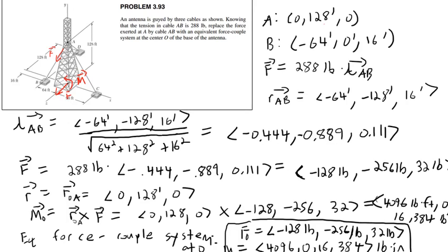Yes. So you're never going to try to change the force. You're finding the moment to balance that out. The question is, we'll never try to change the force, right? Yes, if we're just asking for an equivalent force couple system, no, we'll never end up changing the force. All that we do is add a couple to compensate for moving the force to a different location. Other questions?